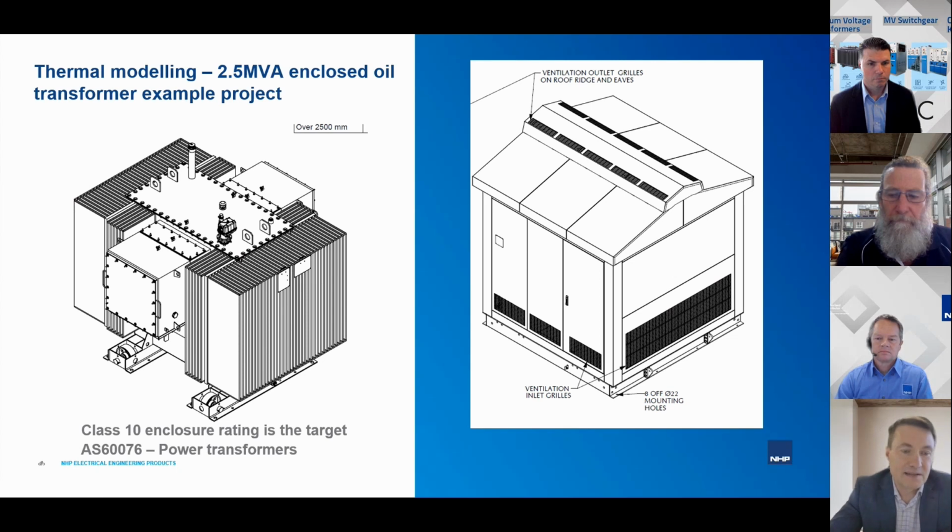As required by 60076. So this was not the case, and therefore the customer asked us to help and try to optimize the enclosure design and minimize the enclosure class, so minimize the temperature rise and therefore minimize the derating of that transformer, which is what Mike and his team have worked on. And I'll pass it on to Mike to talk through the details of the thermal flow modeling that they did and how they achieved the target class 10 of this transformer enclosure.